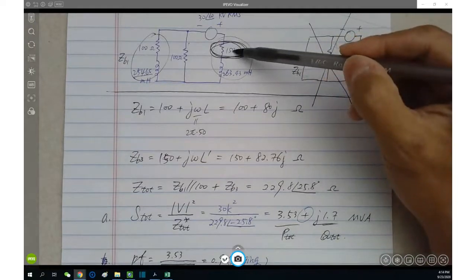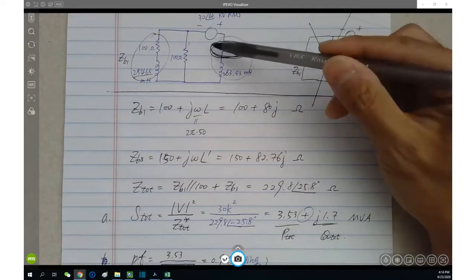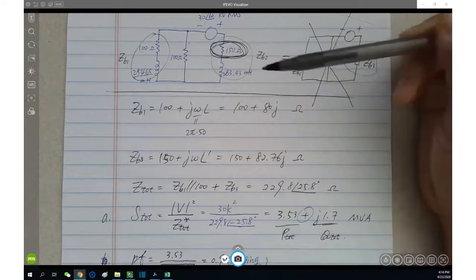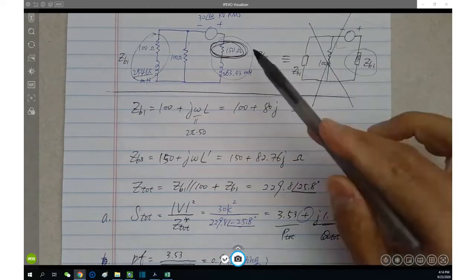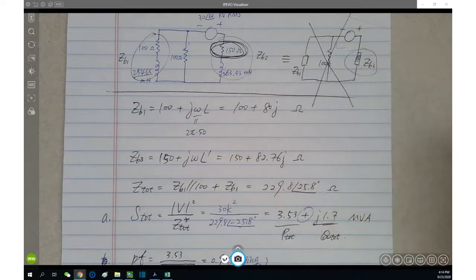And then what else can you have? Find the voltage of it? Well, maybe. But how about the current of it? It's much easier, isn't it? You have the current of R3, and you have the impedance R3, and then you apply one of the versions of the complex power formula. It can do the job, right?